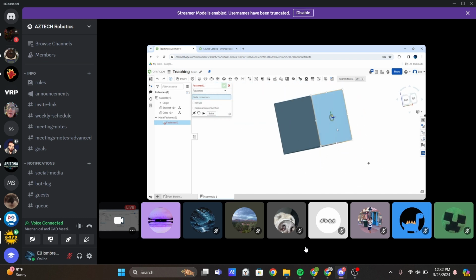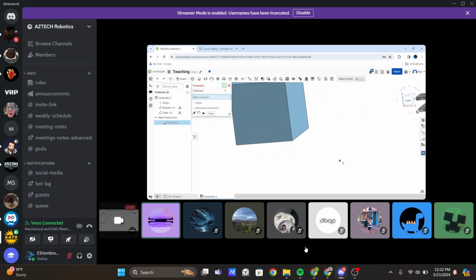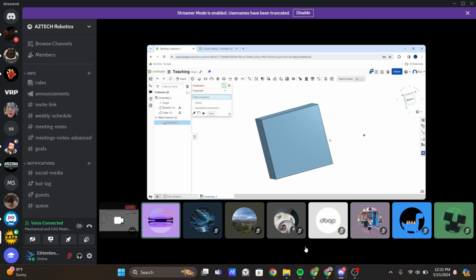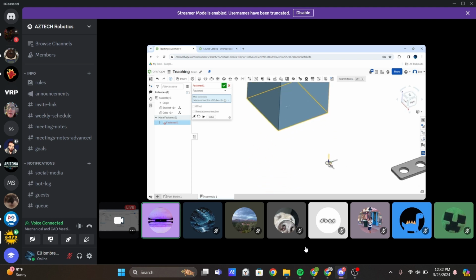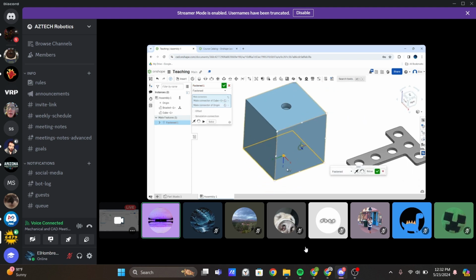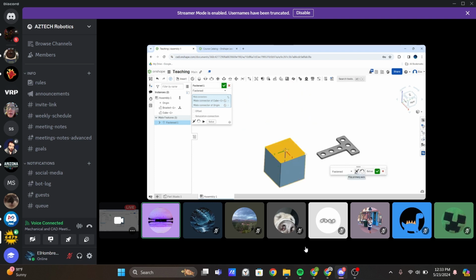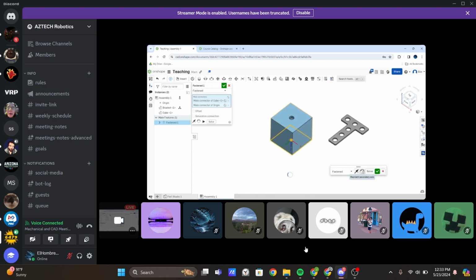So I'm going to start by fixing this cube we made to the origin, just to kind of anchor it there. So I want to go down to the bottom of this, and when I hover over, I can click on that center point, and those little lines you see, those are the X, Y, and Z axes. So if I click that, now that point has one mate connector there, and now I want to put the other mate connector on the origin. The whole point of these X, Y, and Z axes is that you can reorient them here. So I can flip the primary axis, which will basically just flip the whole thing upside down, or I can also rotate it, which you can't tell the difference with because this thing is symmetric. I'll show that again with this later.